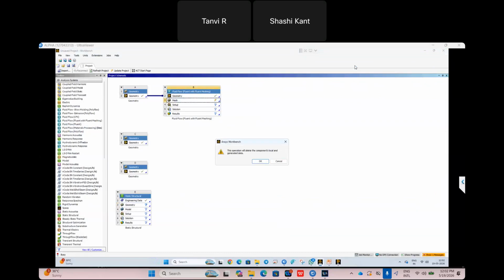Initially I did a reset. I will go once again. I will say generate, generate once again this geometry. Once the geometry is generated inside the meshing process, then we will apply some boundary conditions in the Ansys Fluent setup. We will specify the flying speed of the eVTOL, and the fluid density and air properties.